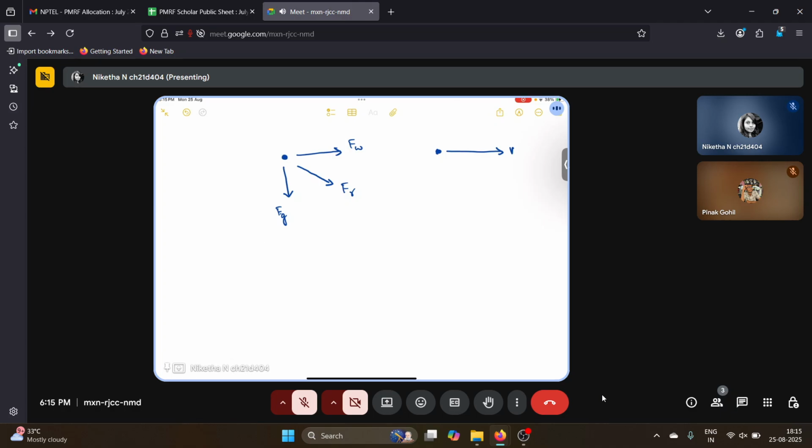It is going off track and coming down. The velocity at which it tends to come down is its terminal velocity, or Vp. We'll see what terminal velocity is a little later. Again, resolving between these two velocities, we have the resultant velocity, which is Vr. This is the same principle that happens in the gravity settler.